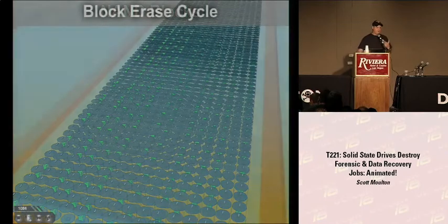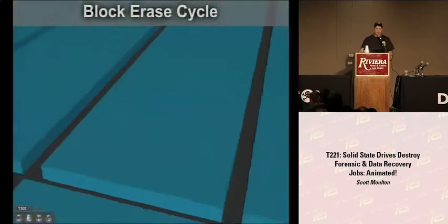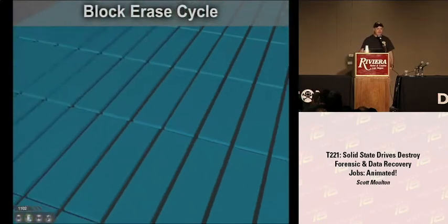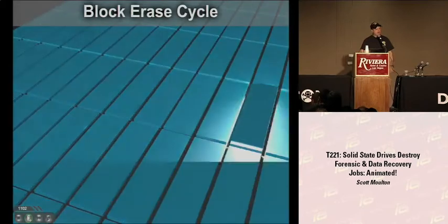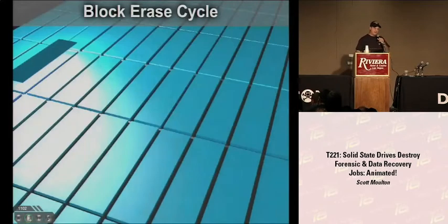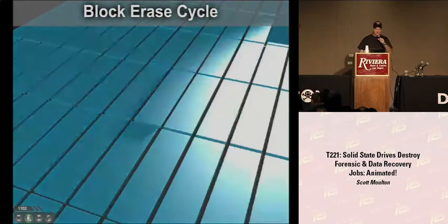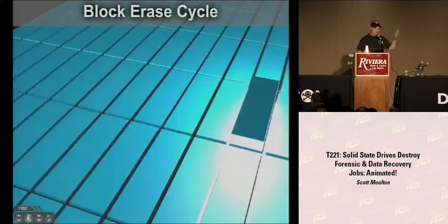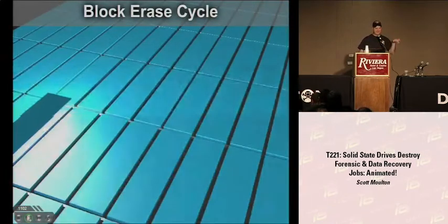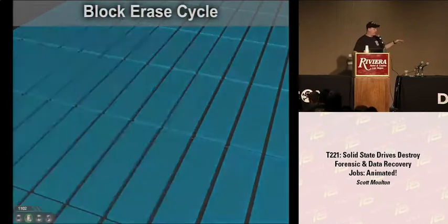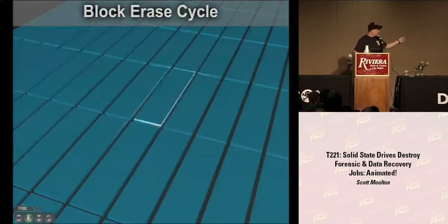But one of the biggest problems we have is that we can't erase a sector. We have to erase things in a block. Now, again, some liberties have been taken here because this is not how it happens inside your chip. You don't have little lids popping off of your plastic Gatorades or anything like that. So these are divided up into blocks, and I am trying to signify what happens.